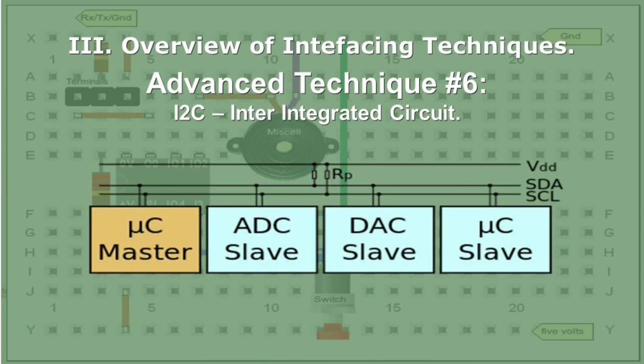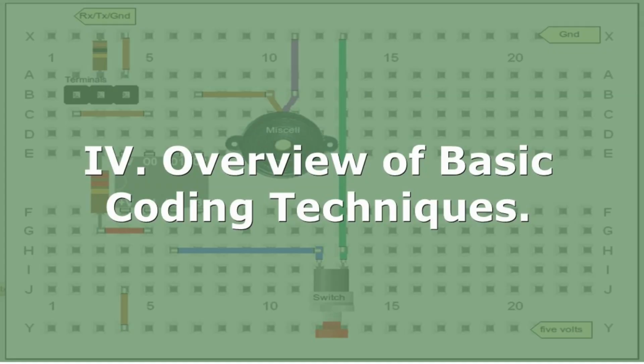I got those from Wikipedia. I didn't create them myself. You don't have a chip select line here. You don't need that anymore. You simply run a clock and a data line. And notice you don't have two data lines. You've got one. In other words, data in and data out go on the same data line. It takes fewer wires to do it, but it will be a little bit slower naturally as a result.